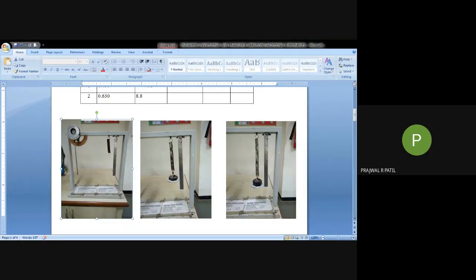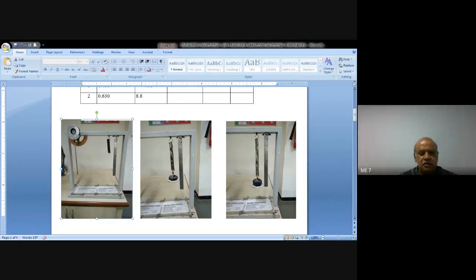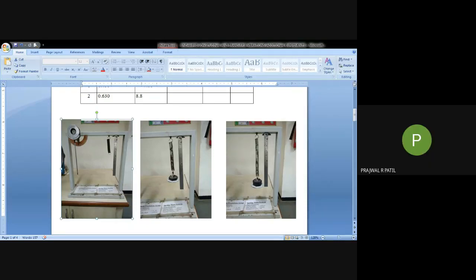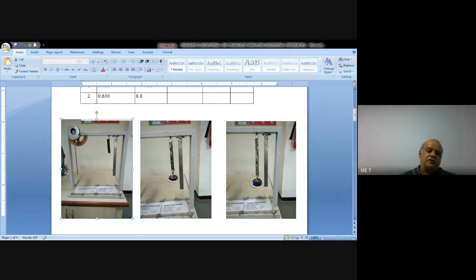So it is the length of the spring when there is no mass attached to it. Okay. So the length of spring in unloaded condition. Okay. So we are going to note down the length of spring in unloaded condition. Then we apply load through a pan. Can you see the pan here? Pan and weight put together, so we have to consider weight of the pan also. Pan weight is 230 grams and weight that is attached is 200 grams.